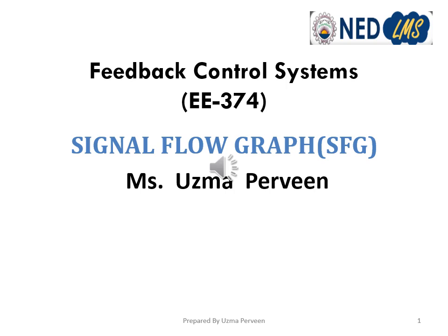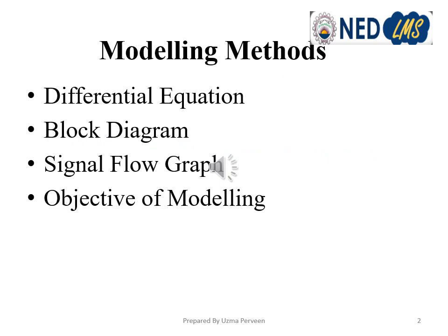So this is a more convenient method as compared to the block diagram, and we will find the transfer function using some rules. While we apply some rules on the signal flow graph, we will find the transfer function, the relationship between the control variable and the input variable. Just to recall, another modeling method, we'll see the signal flow graph now in the next lecture.